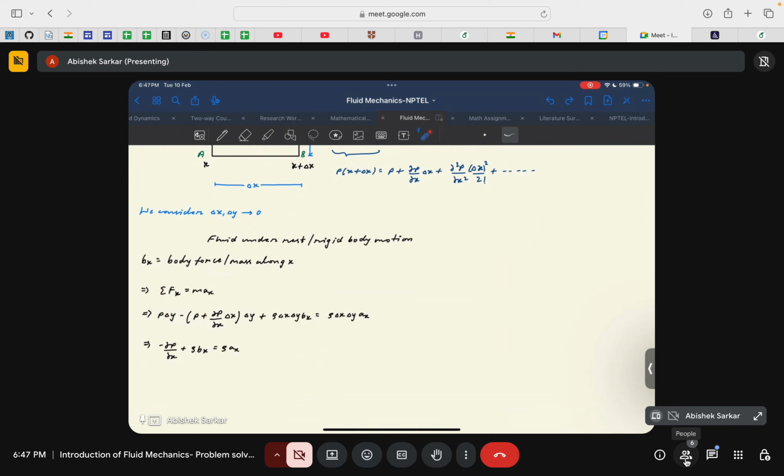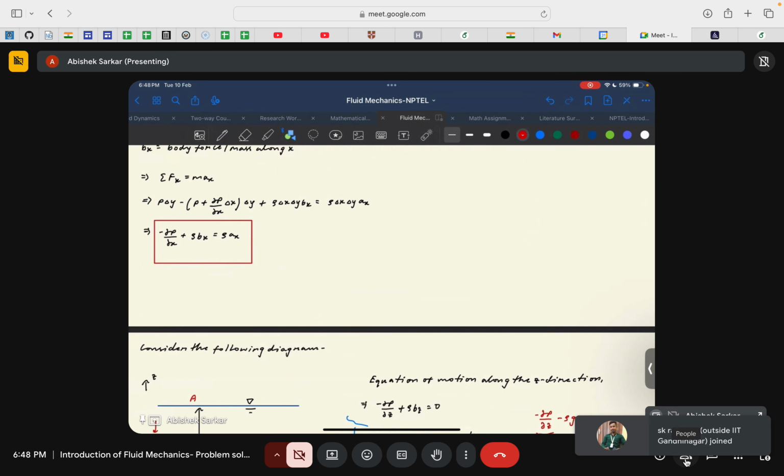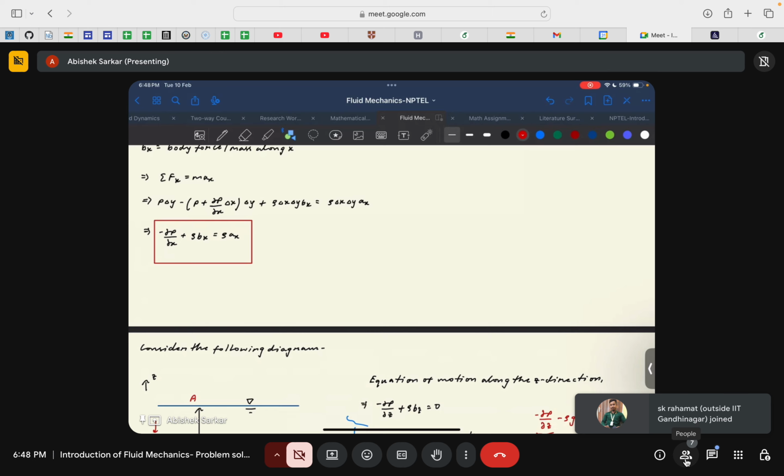For the very first application of this equation of motion, let us just mark it red because it's an equation of motion for fluid statics, generalized because we are considering rigid body motion as well. So it is the generalized equation of motion for fluid statics. For any fluid statics case, we'll start with this expression. If the fluid is at complete rest, with no rigid body motion considered, then this rho a term will of course be equal to 0. Then your pressure gradient will be balanced by the net body force.